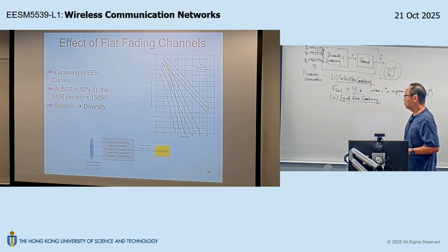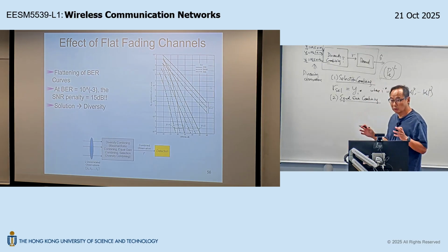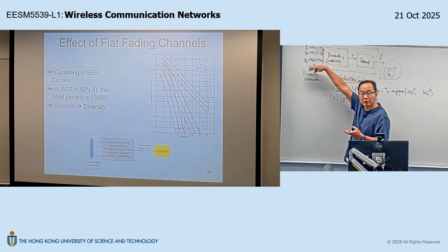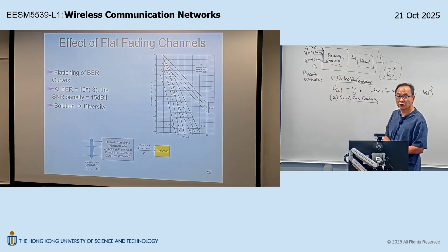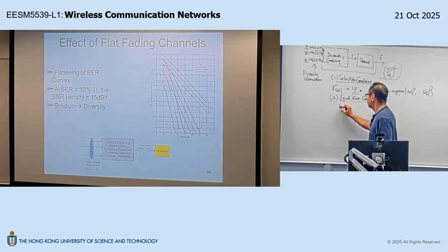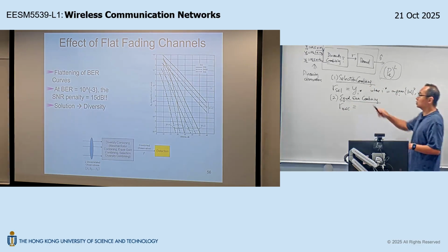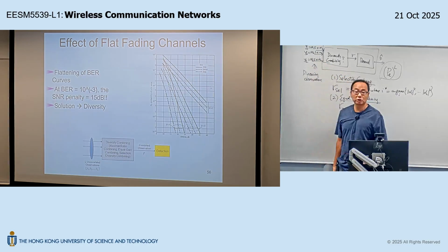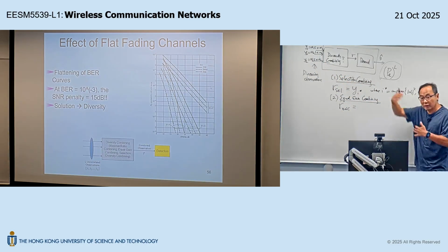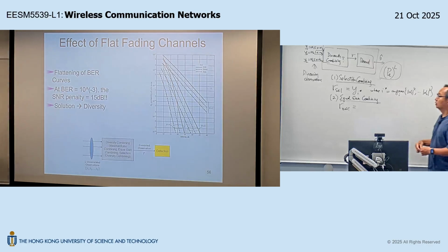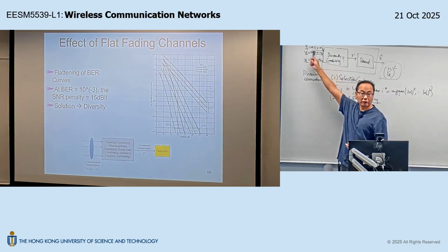So in equal gain combining, what you wanted to do conceptually is add up these observations so as to reinforce your good term. Okay? So this is called equal gain combining. You want to add them up. However, you cannot just do y1 plus y2 plus y3, etc. You cannot just add them up literally because each of these observations suffers from a fading coefficient, right?